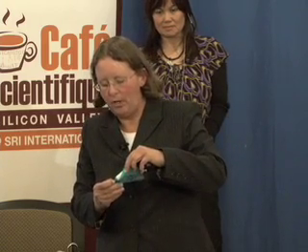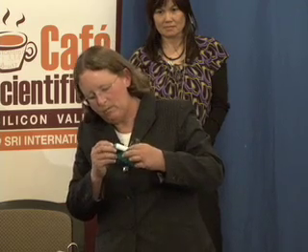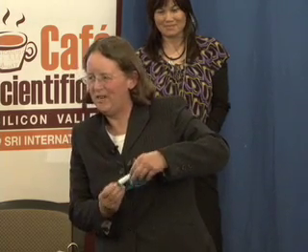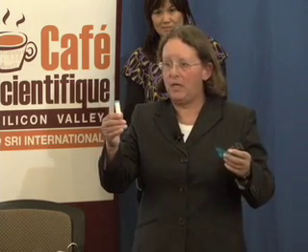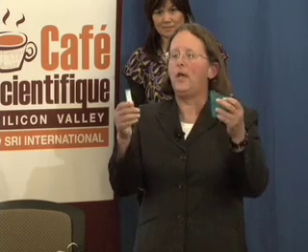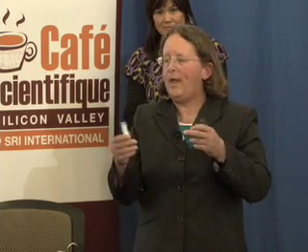And so the carbon within this sampler, and we've taken this thing in and out so many times I can't even get it out anymore. Anyway, it's carbon that's in a steel mesh tube. And so it sits here, and we'll set this out in a home for anywhere from 3 up to about 14 days, depending on the site and the contaminant that we're looking at. And it just passively sorbs the contaminants. So the carbon that's in here has a known uptake rate. And it's different for each contaminant, but that, what's called the Q value, is established by the manufacturer.